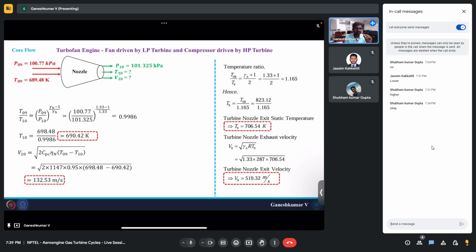So we just added a gearbox and we increased the bypass ratio, and just because of the change in the work done by the turbine, you see the pressure at the exit of the nozzle in a geared turbofan engine has reduced to a very low value. The reason is your nozzle is unchoked. If it is choked, it will have higher velocity. And the other thing is your nozzle inlet pressures are lower. Those are the two reasons why the velocity at the exit of the nozzle is very low compared to the exit velocity of the conventional turbofan. Okay, so this will have an effect on the thrust, right? If you have higher velocity, you are going to have higher thrust. If you have lower velocity, you are going to have lower thrust.